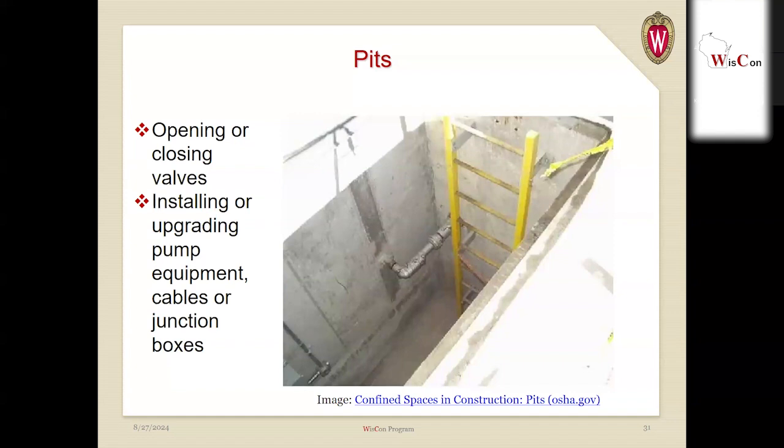And a lot of times, if you have the opportunity to redesign something where someone has to go into a pit like this to routinely turn a valve, it's good to try to design it so that you can control the valves either remotely or above ground. So I've seen in a couple wastewater treatment plants where when they've redesigned them or upgraded them, they've changed it so that they can control the valves without going into a confined space. So that's always something to keep in mind if you have that opportunity. You'd like to design out the confined space hazard.